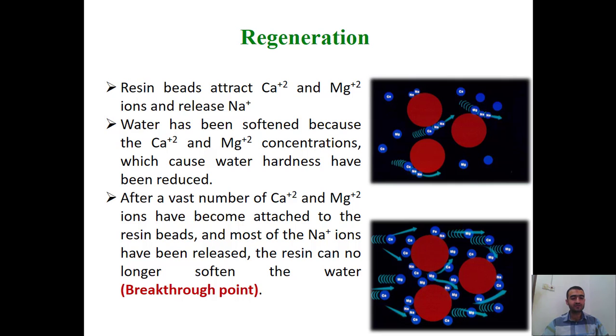Regeneration means that at the point of breakthrough, we don't want to keep using the ion exchanger until it is totally exhausted. At certain points, we have to stop using the ion exchanger and carry out something called regeneration, which means the reproduction of the ion exchanger. So the resin beads attract calcium and magnesium and release sodium. Okay, the water has been softened now.